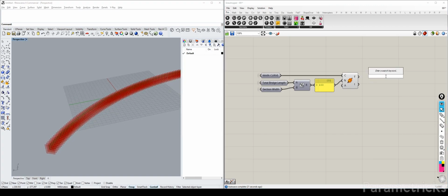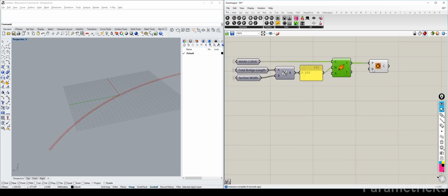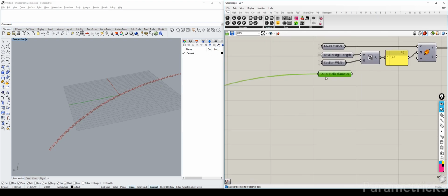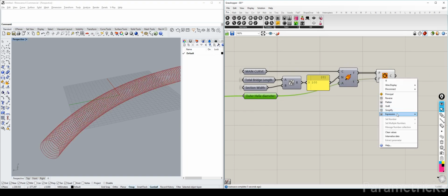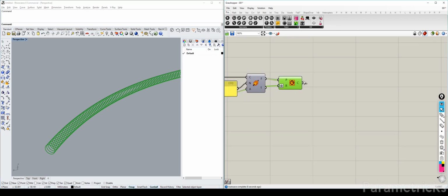One thing we can do is start creating the circle that is going to be defining the major helices. So circle, it can catch a point or a frame. Let me hide this one. And we need the radius, so we can actually grab this. This is actually the diameter, so we need to divide this by 2 in order to get the radius. We can right click on the R, use expression x divided by 2, x being the input, and now we should have 5.4.